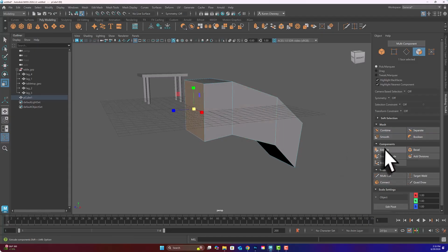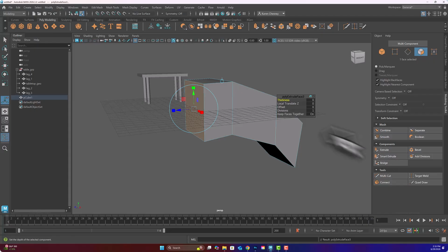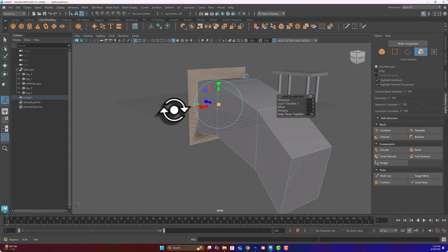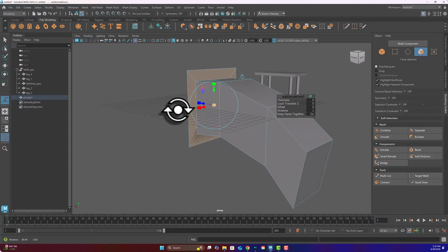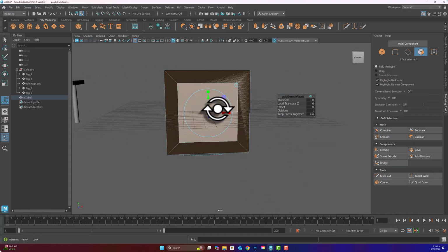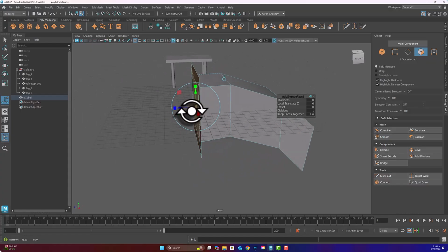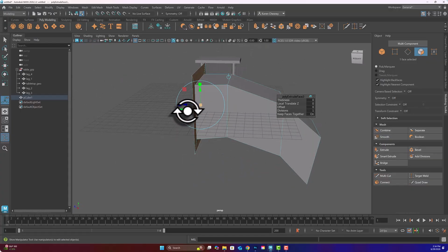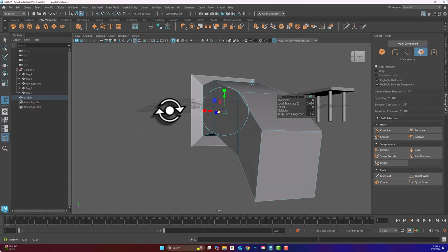Watch what else you can do with extrude. If I say extrude on this one face and I choose the scale icon, which is the little cubey thing, and I grab it here in the middle to scale proportionally, look what it did. It took that face and it just made it bigger. Now, Maya doesn't like just that, because see all the little sketchy things? Maya's like, no, I'm not real keen on this just yet. We have to move it. So if I move it a little bit, okay, I have duplicated the face and I've made it bigger, which makes a nice bevel.